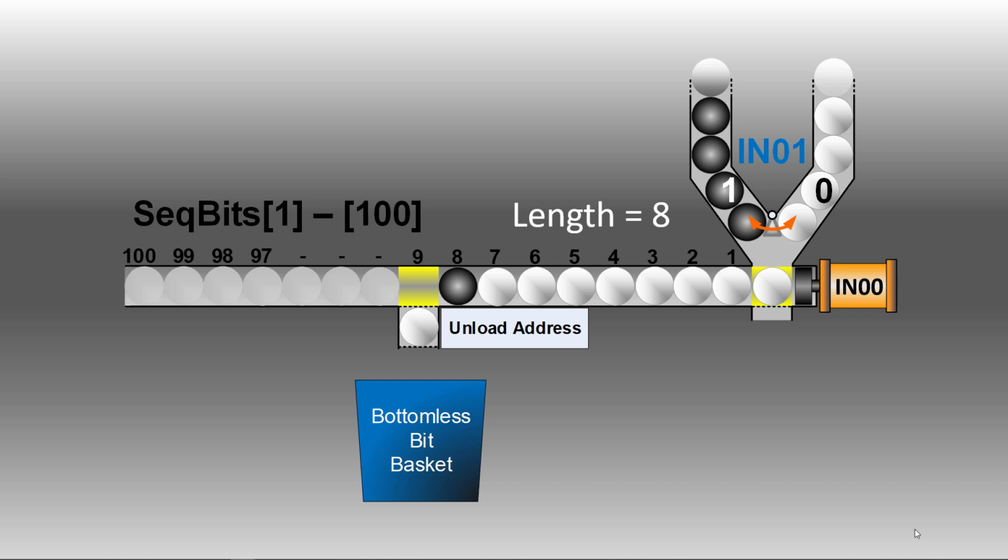So every time you create a Boolean data type, you are using a 32-bit word. Now in Micro 800, you don't really have the opportunity to shift bits around in a data type like a double integer or an integer or an unsigned integer, single integer.